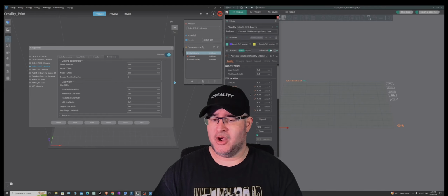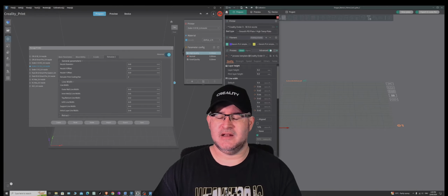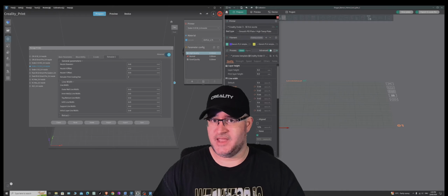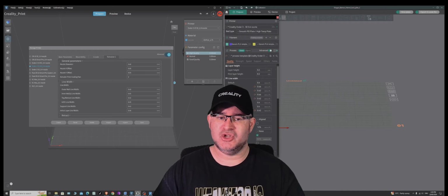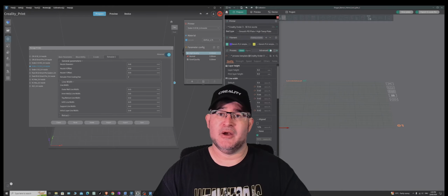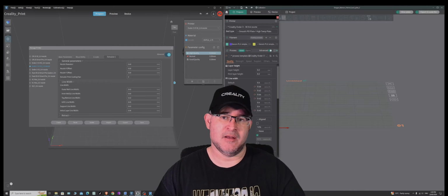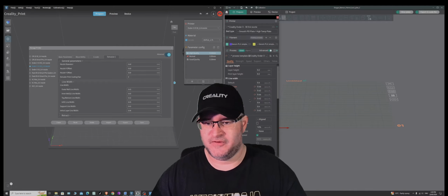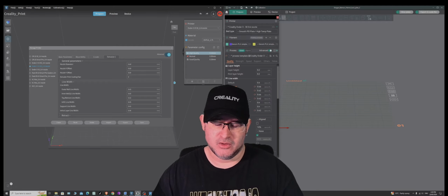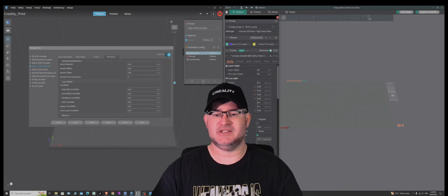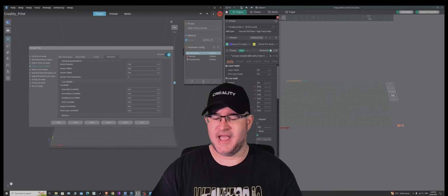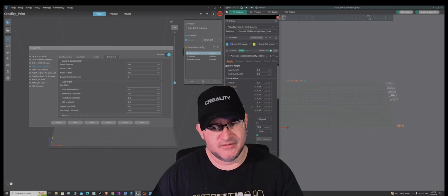But in another video, I will show you how to set these parameters up for your line width for different models so that you can get less layer lines throughout your print, and you don't get as much layering through the curves and bridging throughout your prints, which will affect the surface quality of your print as well. And obviously by adjusting the internal infill line width, that can affect the speed of your infill as well, which helps with print times. So that's for another video.